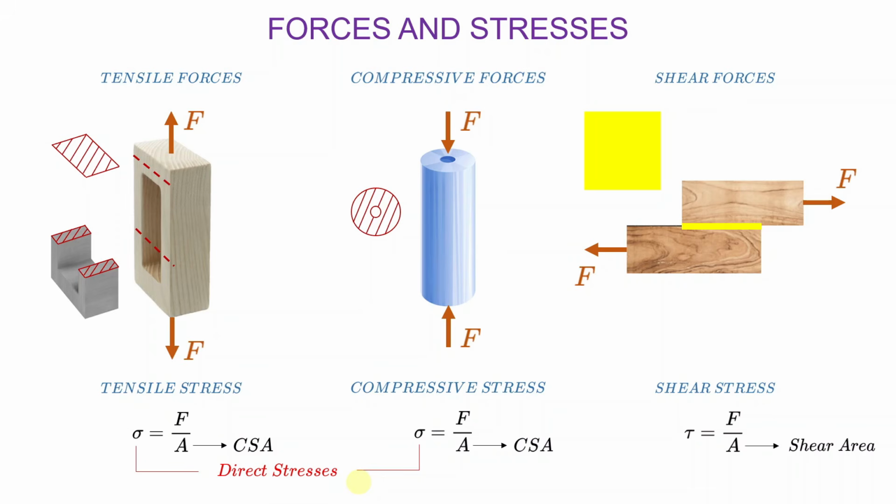If in a question they ask you to calculate the direct stress, just know that you have to calculate either the tensile stress or the compressive stress, depending on whether you have tensile forces or compressive forces acting on that particular object. So do not be surprised if you hear the expression direct stress. This is just referring to either tensile or compressive stress.